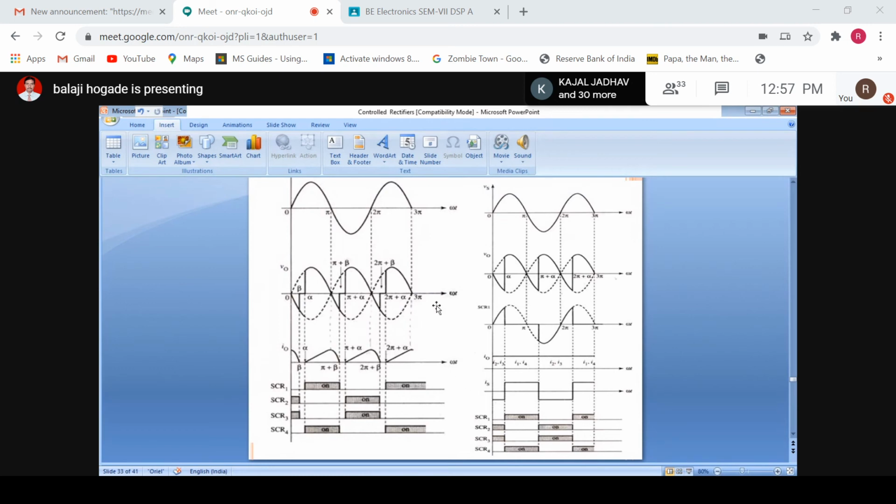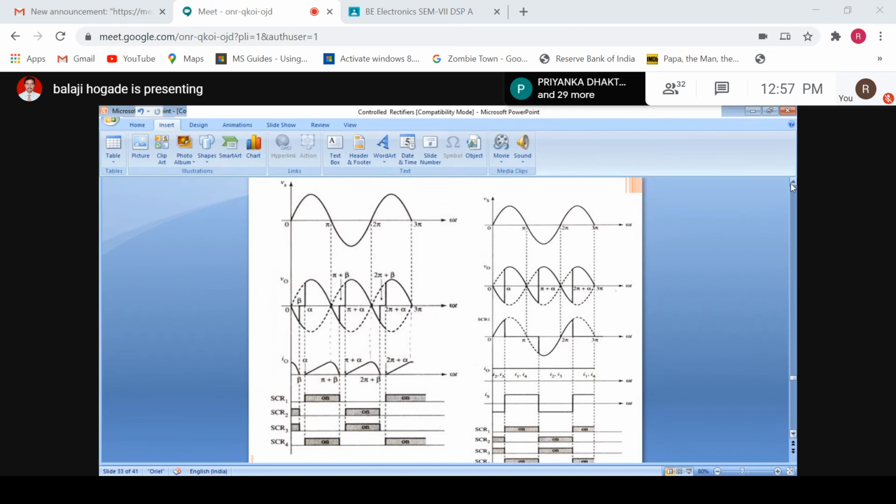That is because of the value of the inductor. So here you can say it is a continuous current conduction mode because the value of the inductor is very large, and in the previous case, that is low inductance value, the operation is discontinuous current conduction mode. The circuit works in the same way, just current can be continuous or discontinuous depending on the value of the inductor.